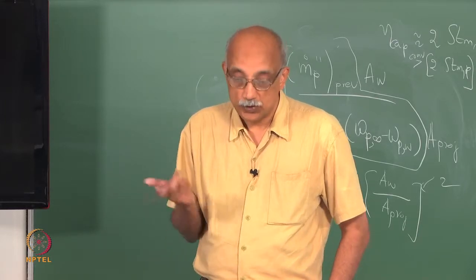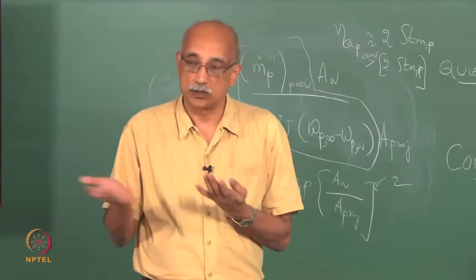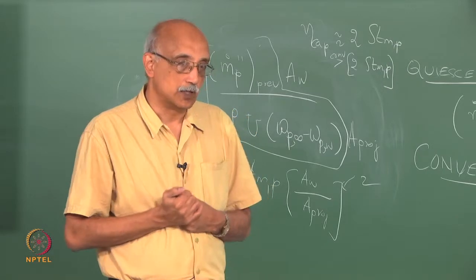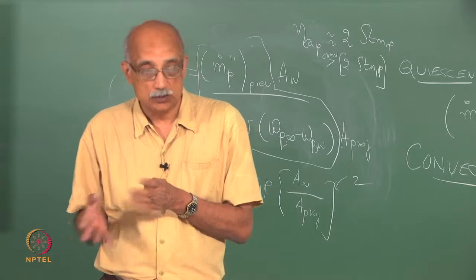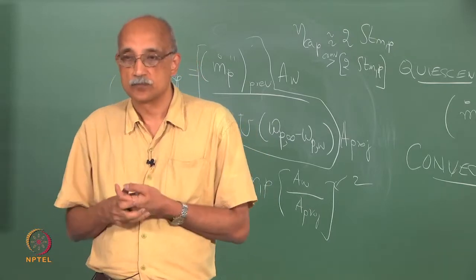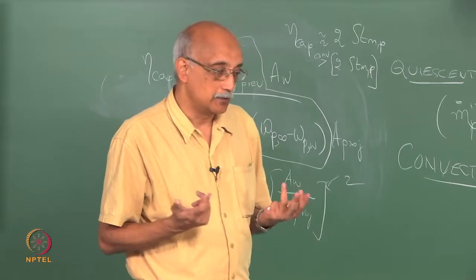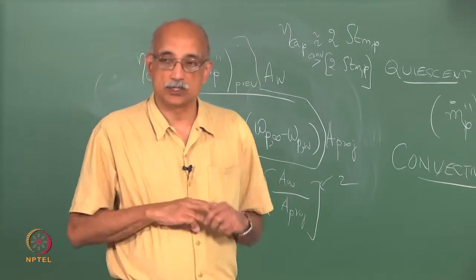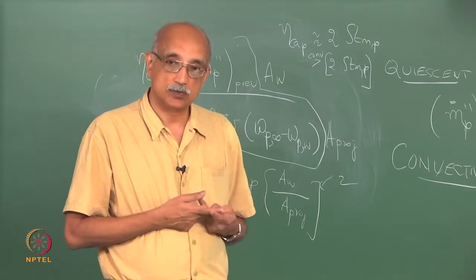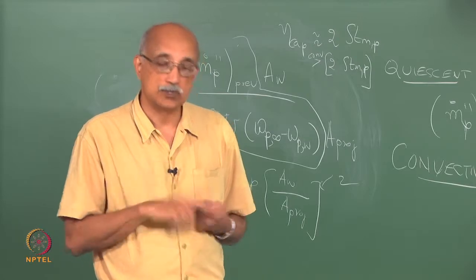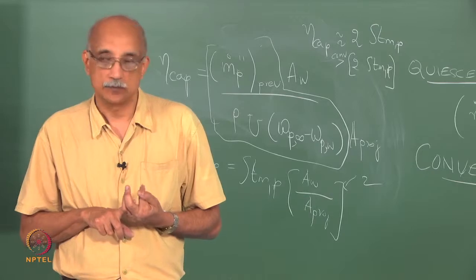And then we talked about cohesion, which is the adhesion between particles in a flow or in a suspension, and the fact that many of the forces are common to adhesion to surfaces, but some are different. In particular, cohesion is characterized by 3 fairly unique forces that have no counterpart to surface adhesion, that is surface tension forces or capillary forces, viscous forces and spring like forces, right.